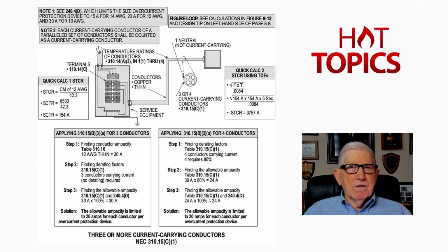So your motors and things can start. So if you had a 30 amp circuit breaker, times 3, 90 amps, any motor load or anything that had an inrush value below that 90, and the acceleration time of the load was quick, fast, then it started.